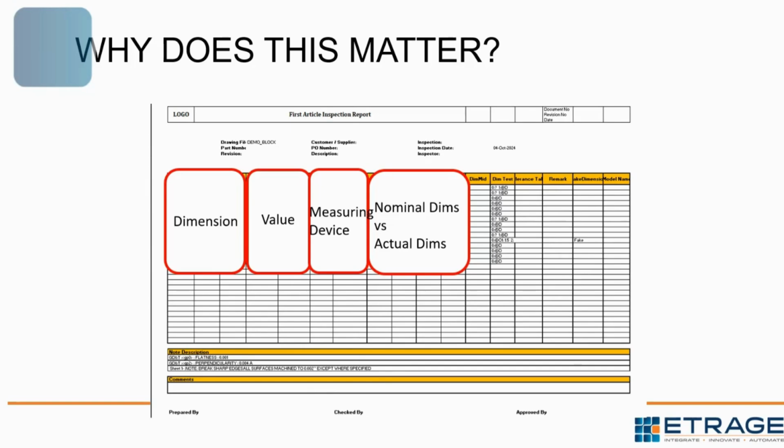And you can set up your inspection routine in all those softwares to just measure based off of that inspection routine. And then when they all measure and store the data, you can export the data from all those softwares into Excel and then just copy paste into this report right here.